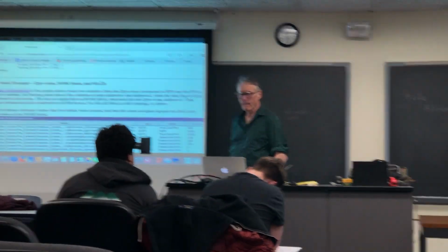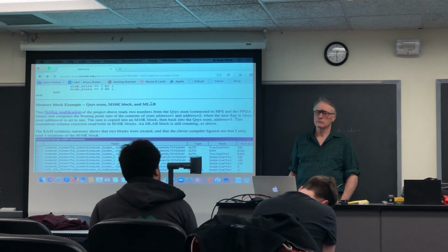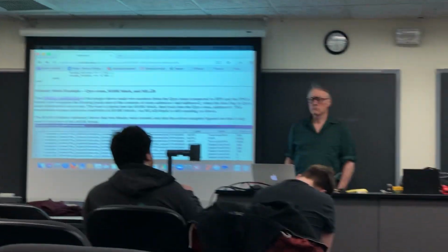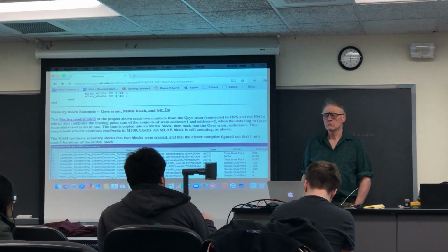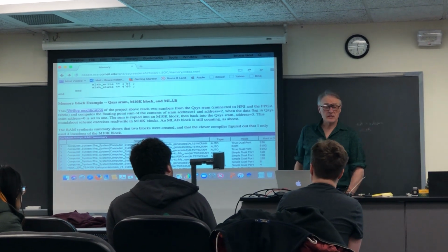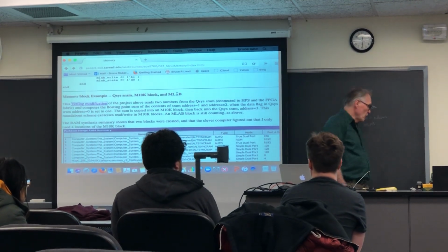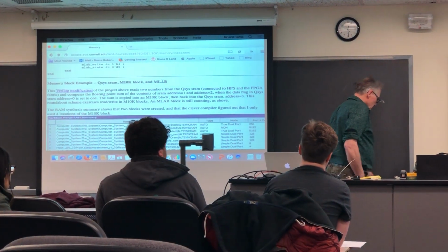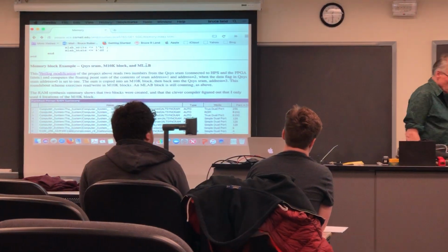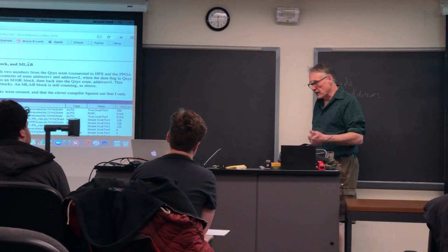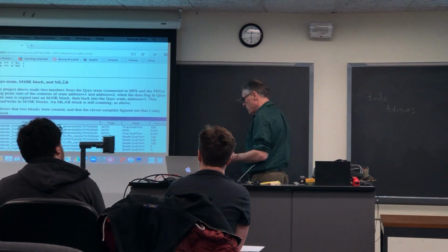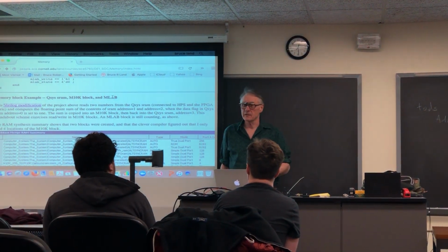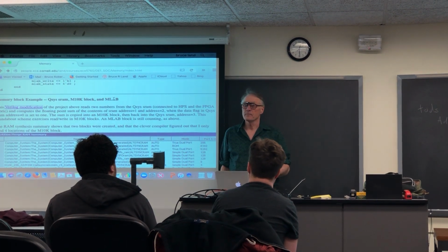So for the system we were talking about last time during class, where we would allocate a separate memory block for every unit of parallelization for the Mandelbrot set, which of the two memory blocks would be more appropriate? It depends on the size of your block. If you were going to put all of display memory into block memory, I would say M10K blocks, because I don't think there's enough MLab space.